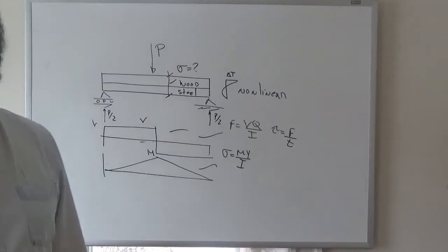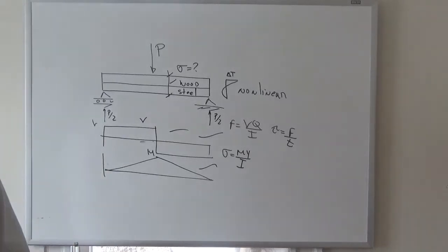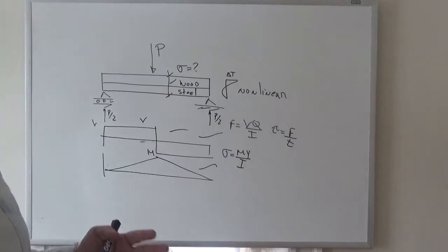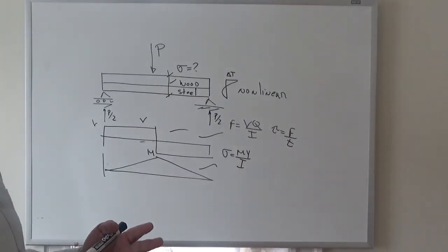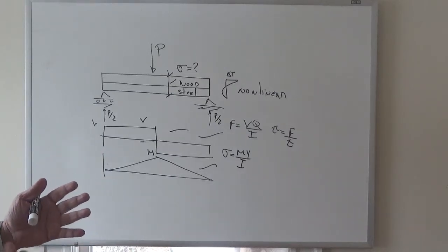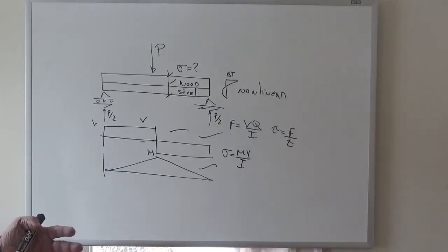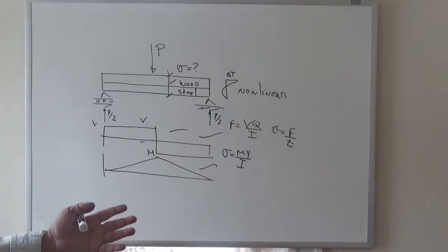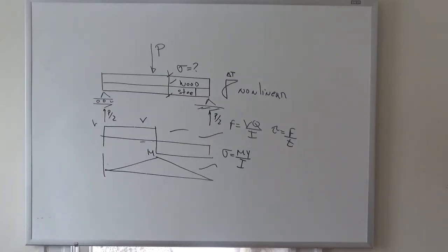So, if you really want to be clean mentally, you have to just say that all there is are just statically determinate quantities, not statically determinate structures. That the use of the term statically determinate structure is just a conventional thing. That what we mean is, if we can calculate shear and moment diagrams using only statics everywhere, that's good enough. We're going to call it statically determinate structure. Okay?